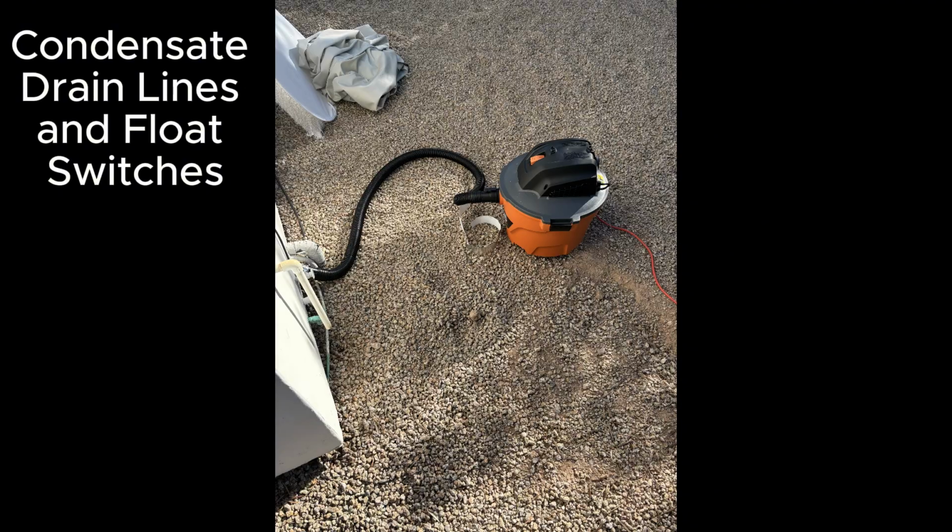So what you can do if your thermostat's turning off, something you could just try to see if it will fix the issue, is take a shop vac, put it on the suction setting so that it sucks air, connect it to wherever the exterior drain is on the home or the structure, and use a hand to seal it, or use some tape, get that really sealed, and just turn it on for 5 to 10 minutes and try to clear the restriction by sucking out whatever is restricting the drain line.